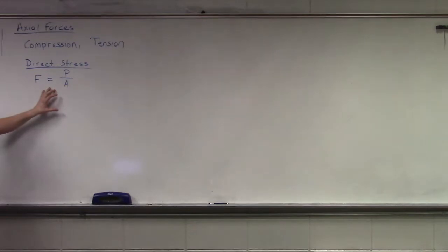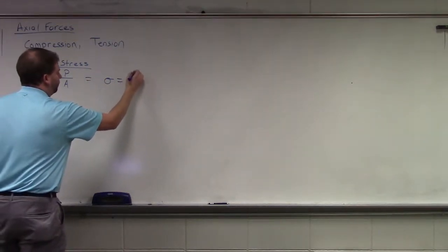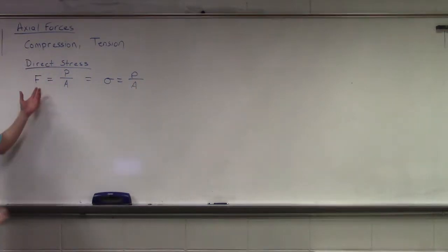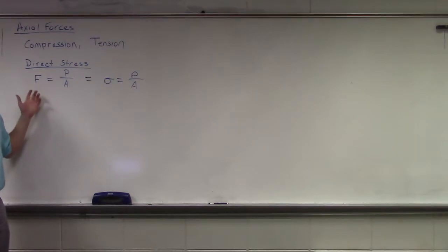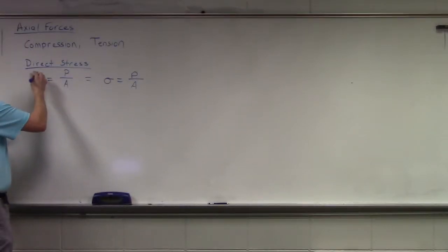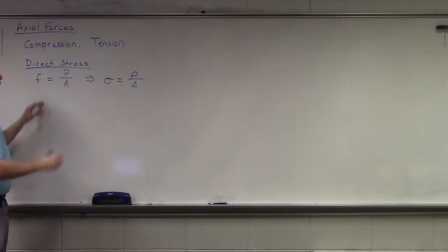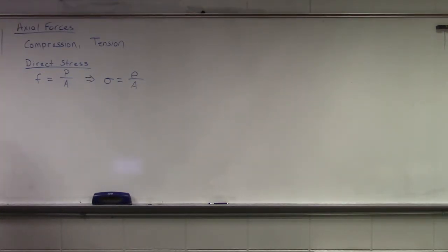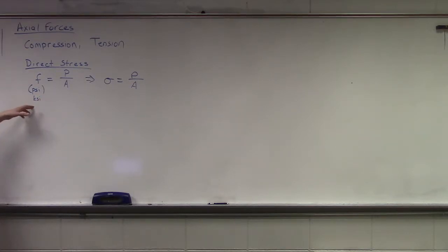This should look fairly familiar; we've come across it before. I prefer that they use a different symbol to model the stress, because using the F can cause confusion in that you may think of it as a force. Oh, I'm sorry, they use a lowercase f, don't they? We'll defer to the lowercase f to be consistent with their terminology. Our units here are in PSI, they may be in KSI, kips per square inch.